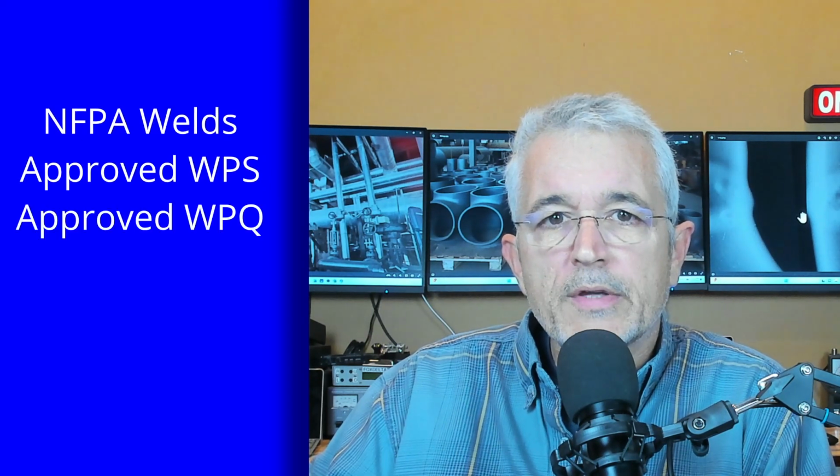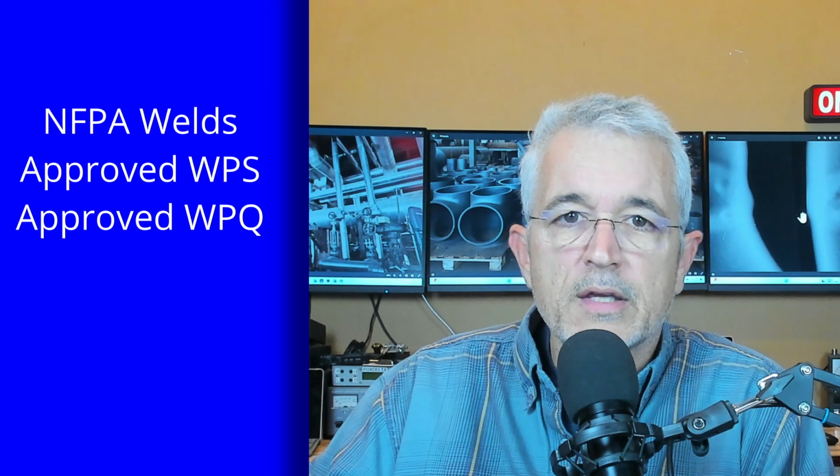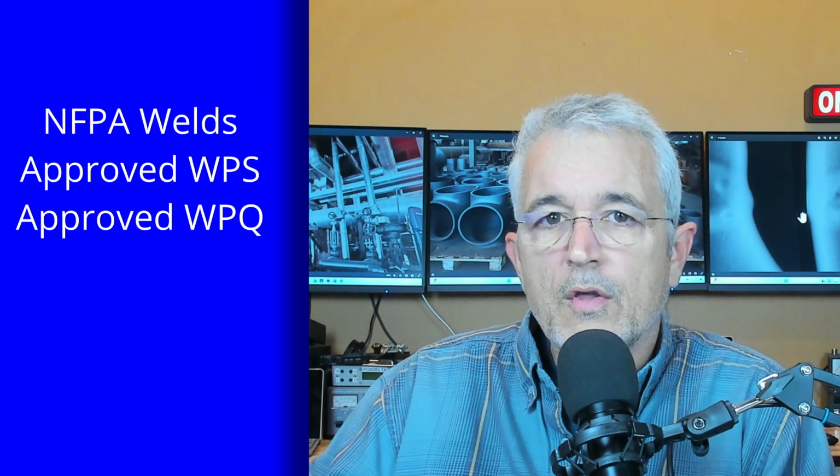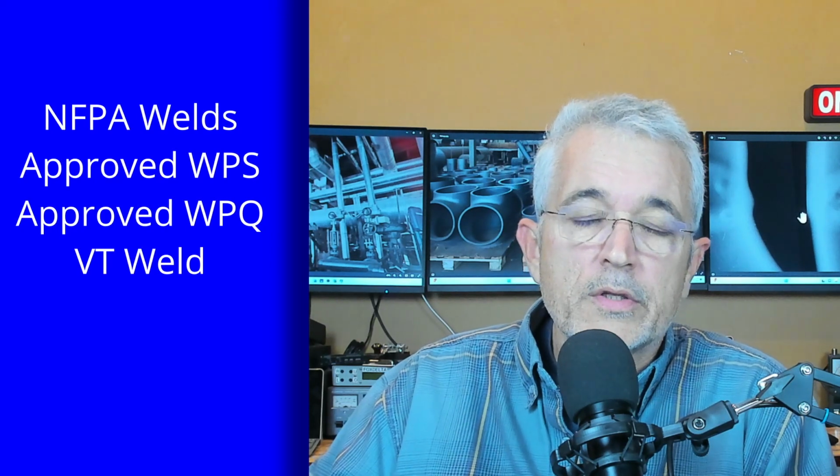What are my welder qualification limitations under NFPA? Filler metal, base metal, thickness, direction of travel. What is the visual acceptance criteria for the welds based upon NFPA design code? What is the tolerance for weld reinforcement, porosity, slag, cold lap, arc strike, lack of fusion? These are all really relevant questions for the welder.